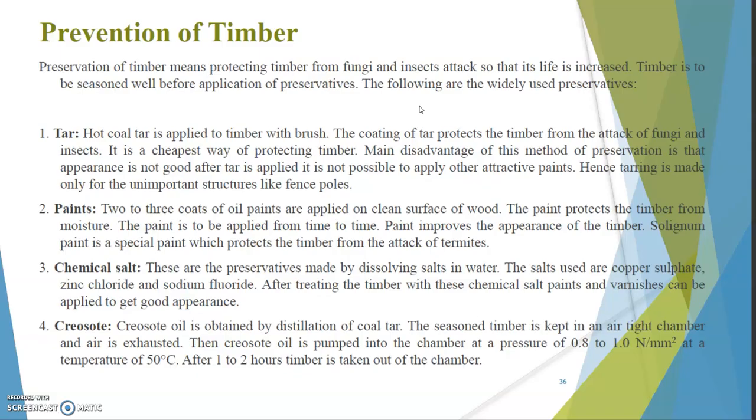Because of appearance issues. Then paints, of course, we have paints, but the condition with respect to the usage of paint is you should go for a number of layers before going for the actual paint application. People may call it a prime coat, so you have to scratch the surface first to some extent, then you have to apply the primer coat.